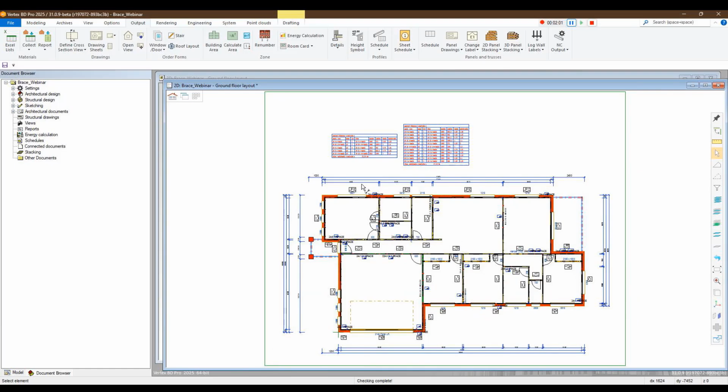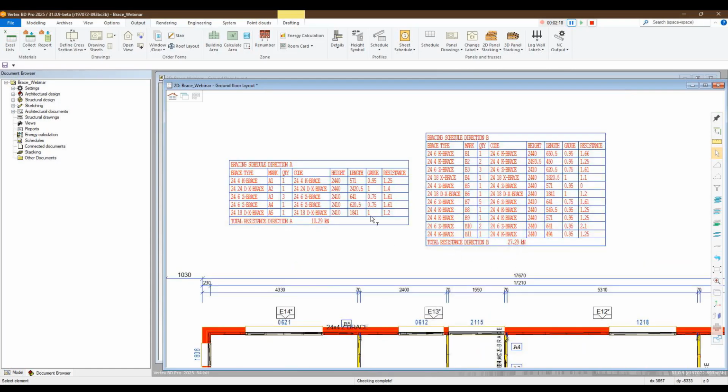So that is a way of doing it. So if you have a plan that's been provided to you by the builder or whoever your client is, and you already have the bracing values, this is basically all you need to do to double check that you've exceeded or at least achieved the amount of bracing that you need in the direction that you've got, based off the values that they've told you.